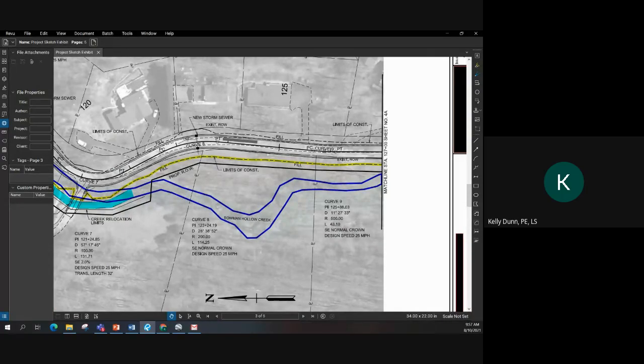So yeah, in this case, it may be okay as shown, since the profile is shown in the roadway improvement, are mostly to be constructed by raising the proposed vertical alignment several feet above the existing roadway, which may eliminate the need for cut slopes on the uphill side, but doing so will most certainly require extended road closures, detours, the need to continue access to connected driveways and streets during construction, and a lot of flagger hours, all of which will drive up the PE traffic estimate from developing a MOT plan and the maintenance of traffic estimate as part of the construction estimate, or part of the maintenance of traffic actually implementing it during construction.